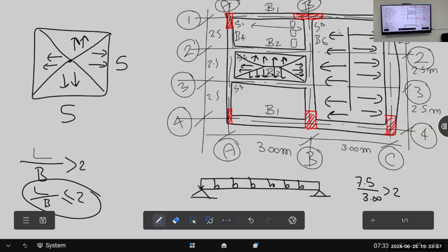The beam is a support for the slab, and the beam is supported by the column. If I am in the middle here, my load is equal on the beams. I am moving now, a moving live load. So 2-way. If I have 4 multiplied by 4, my load is divided in 2 directions. In this slab here, see the length of the slab? Assume it's long here. For sure, 100% goes to this beam. This slab is a 1-way slab, because it's very long, divided through the weights, 1-way.